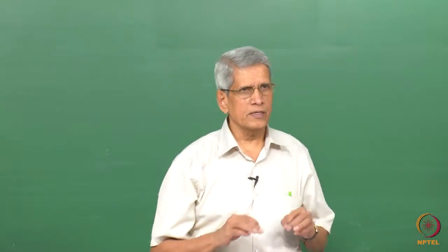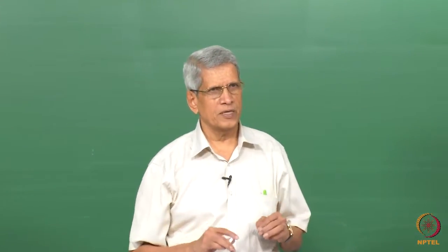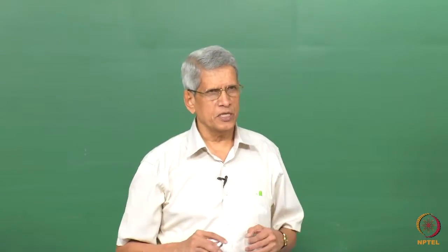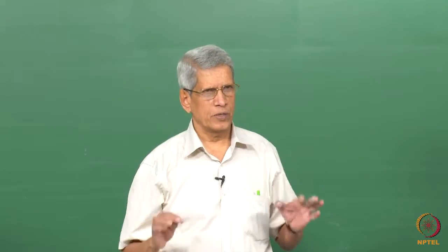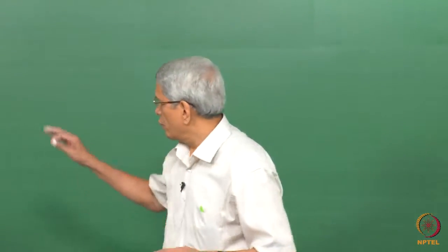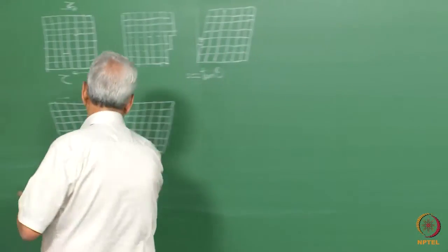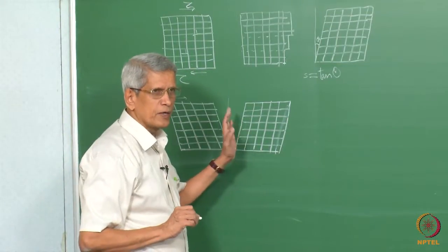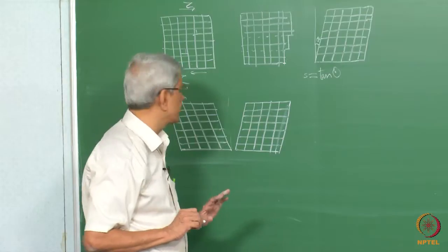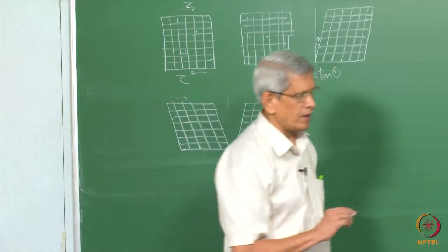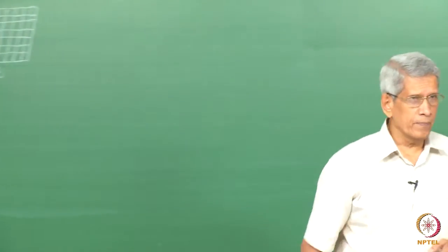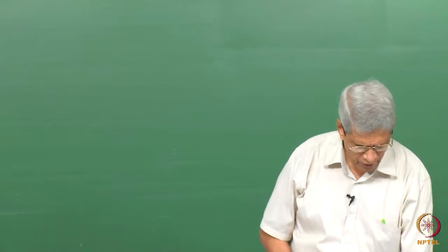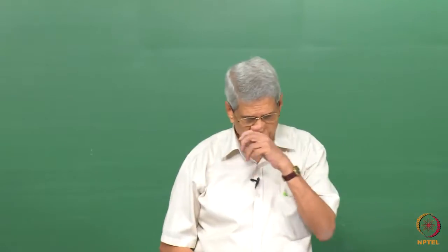This sort of deformation, which takes place in a material by homogeneous shear, is called a twin. So we have looked at the external shape, and now we have considered the unit cell also, right? So only the orientation has changed. This sort of deformation becomes very important.